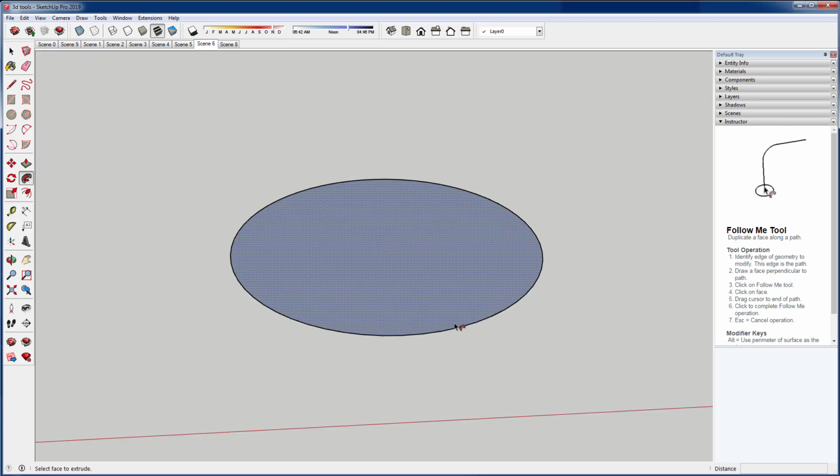And one popular one that people always want to know how to create: how do I make a sphere in SketchUp, since most of the tools are flat objects that are push-pulled into 3 dimensions, but you can't do that with a sphere. So the easiest way that I know of to make a sphere in SketchUp would be to rotate a circle around a circle.